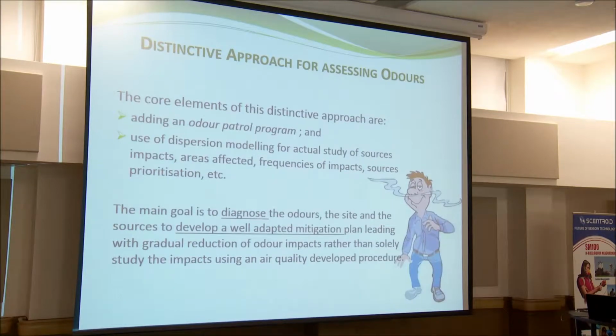So the distinctive approach, the core element of this, is to add the Odour Patrol program, to do ambient monitoring. And then use dispersion modeling, but not only to produce maximum impacts just for doing an assessment like that, but to actually study the real results and compare them to what you have actually observed in ambient air.